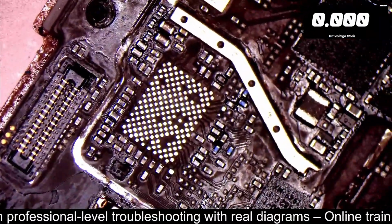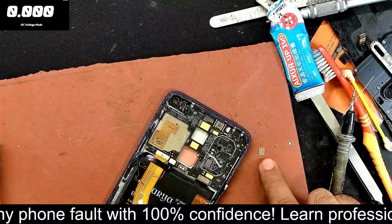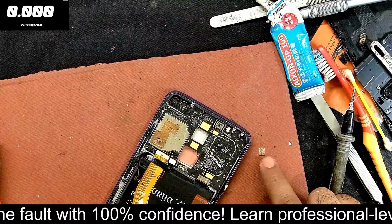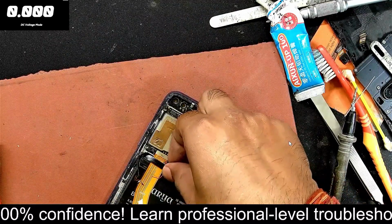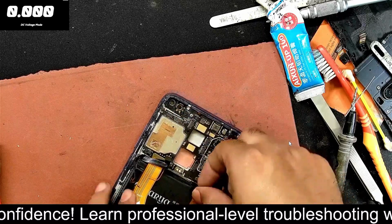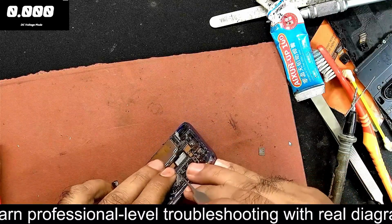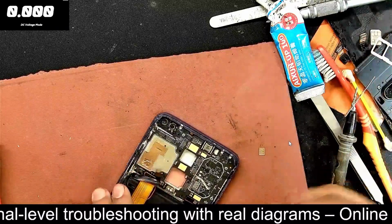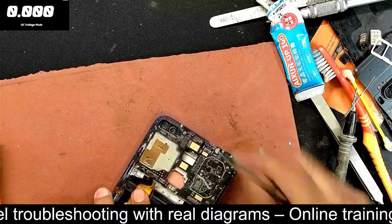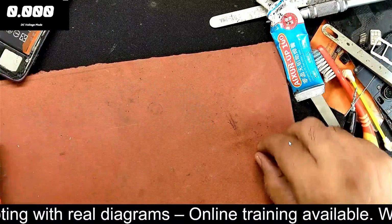So we reball it first. So, we reball this IC first. If after reballing the network comes, that's okay, otherwise we replace it with another IC. Reball it first.